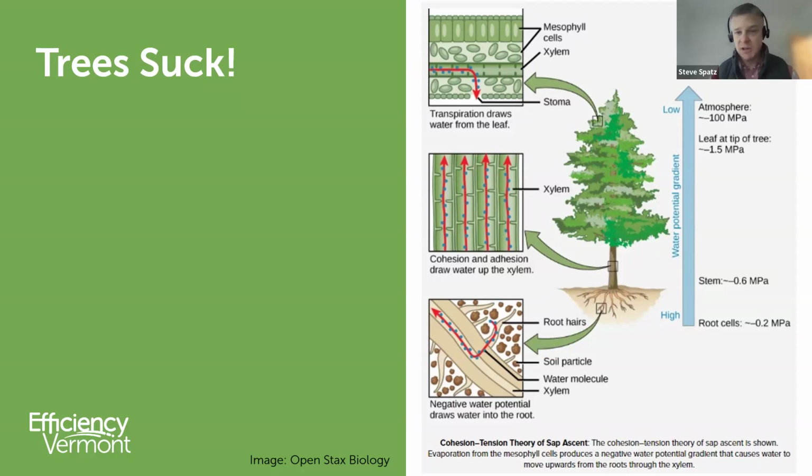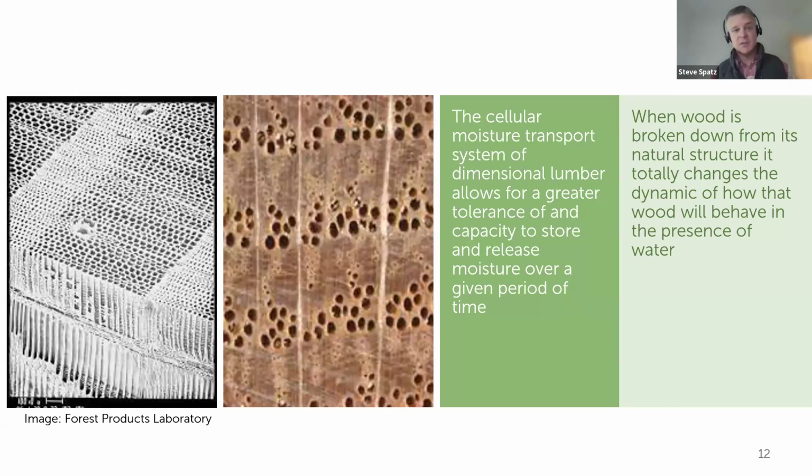We're going to talk about pressure difference and capillary movement as far as how it relates to buildings as well. But the actual moisture and water and nutrient transport through the structure of the wood is inherent to what wood is as a crop, as a resource, and it also has a significant amount of influence on the durability of how wood is used in structures. Wood in its raw form has the capacity to load and retain and manage, by loading and then drying diffusion over time, a huge capacity of water.